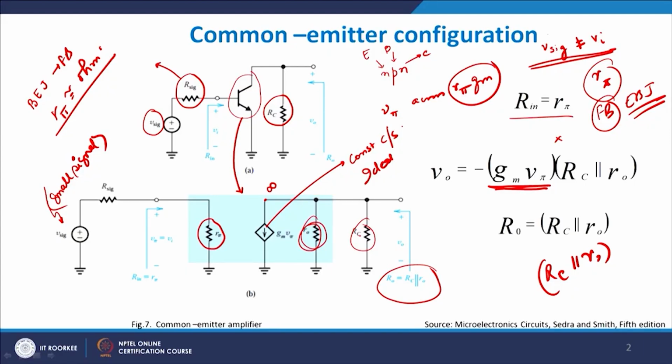So what we have therefore assumed is that the current source is an ideal current source. As a result, the output impedance is infinity. Since it is a constant current source and the output impedance is infinity, when it is in parallel to R0 and RC, that vanishes because it is quite a high quantity. In parallel combination that does not stay to a larger extent; it is always less, because in parallel, you remember, it is less than the least, and in series it is larger than the largest. In this case it is less than the least, and therefore we just neglect that particular case.